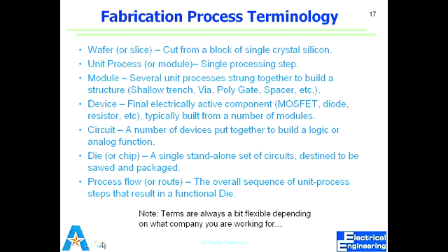Now shallow trench, so we'll see all these things closely, but when I say shallow trench, it entails oxidation, and then lithography, then etching of oxide, and etching of silicon, then filling with silicon dioxide. So just trenching would essentially mean a bunch of processes that go into making that. That will be another goal, that you will be comfortable in knowing many of these modules.